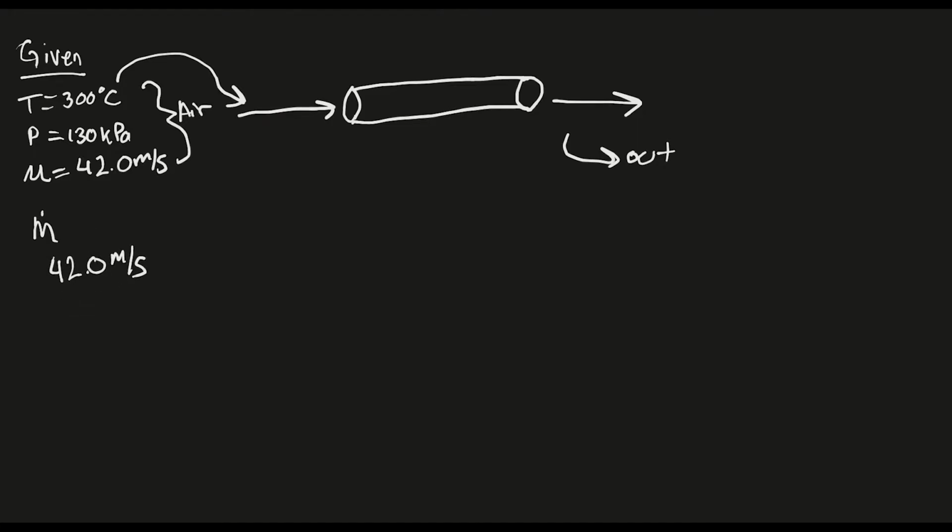Okay, you know what? I want to make it easier for you. Let's move this out of the way. We have 42 meters per second. Write it like this because you'll see why. And then we're going to multiply that by the area of a circle because it's going into our pipe, and the pipe's a circle. But what's the area of a circle? Well, pi d squared over 4. There's another variation, pi r squared. Google it. But this is one version, pi d squared over 4.